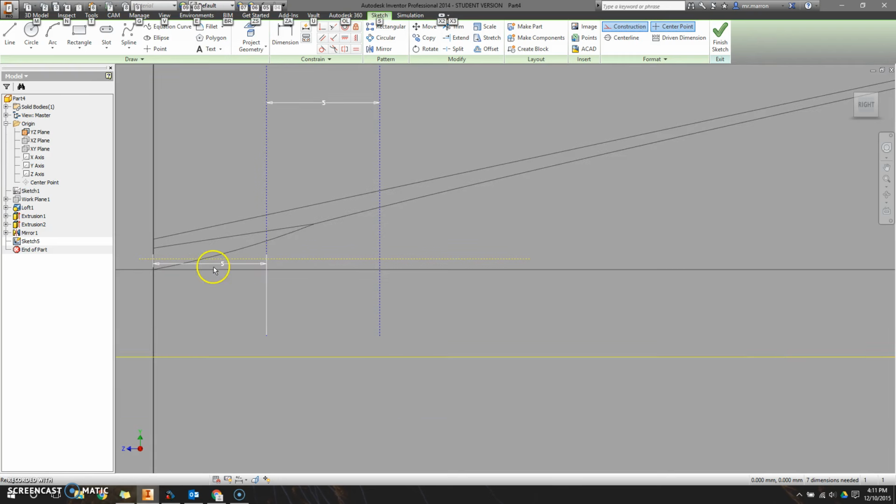So now that I have my construction lines, I'm going to go ahead and start my drawing. I've made myself an intersection here from which to start. So I'm going to go ahead and create a circle here and draw it probably right about the size of my body here. Now you can see that when I drew that circle, it came in as a hashed line, which means it's a construction line. So once again, I forgot to change my drawings from construction into model, so I'm going to simply fix that by clicking on it and then unchecking the construction box. So here I have my starting point for my front wing.